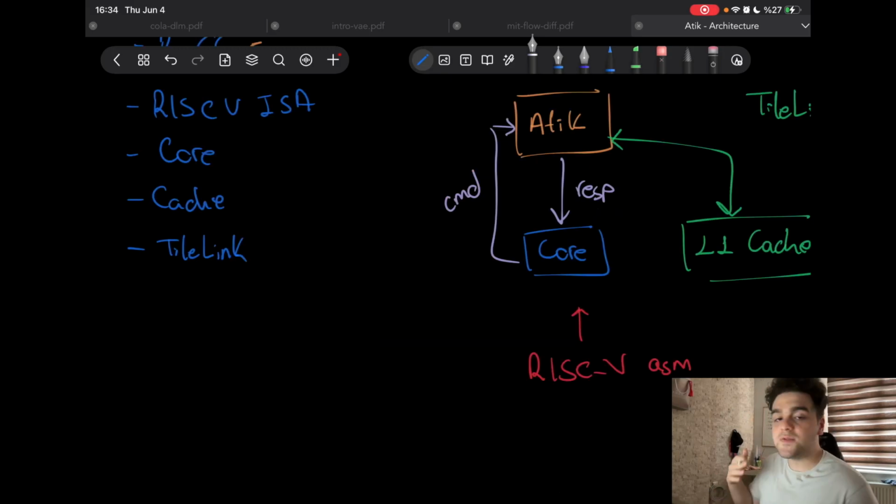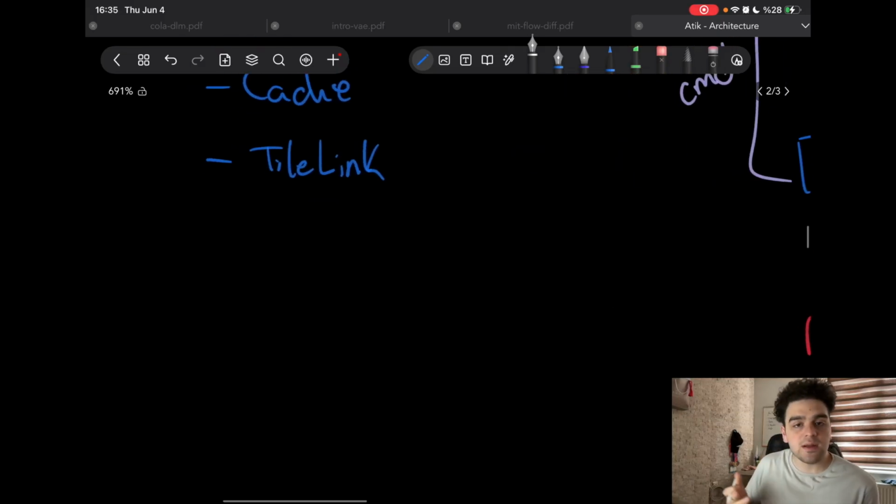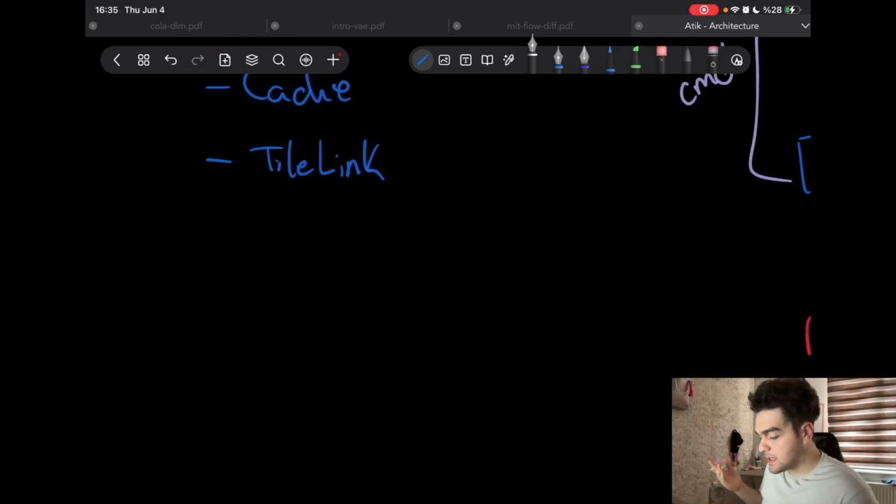Now, after we have reasoned about how the modules should talk with each other and the interface between the accelerator and the core itself, we can think about the instructions, and which instructions are going to trigger this specific accelerator. Because we are dealing with the RISC-V instruction set architecture, and because we are using the Rocket Chip microarchitecture, we have specific instructions that are reserved for us.